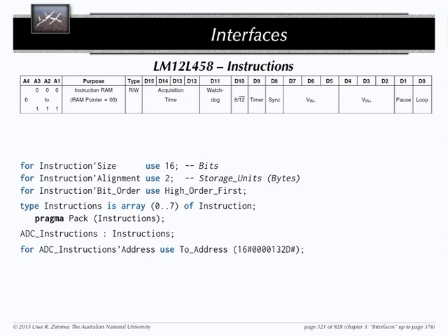Then finally, after all of this type, because so far we haven't actually instantiated anything, we define a variable, ADC instructions. Cool. And now comes the grounding. We say this variable is not supposed to be allocated somewhere by your compiler. This variable is supposed to be happening exactly at this address. This will be nailed hard to this address in your memory.